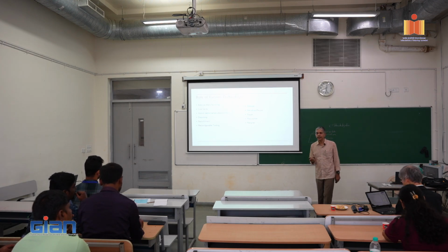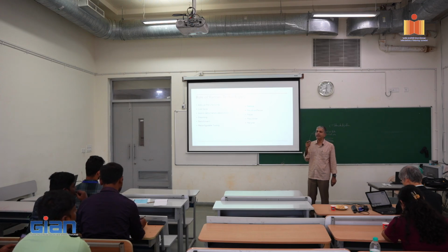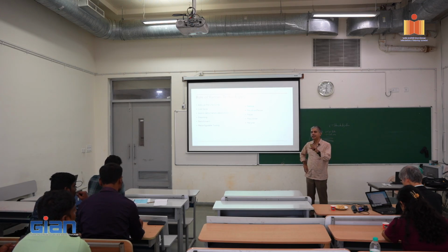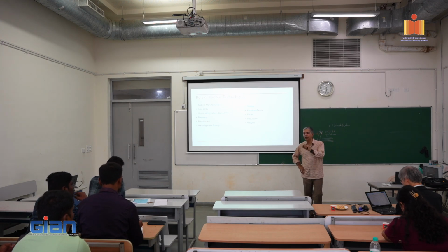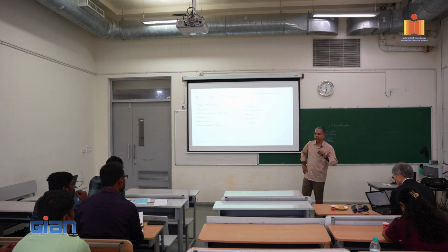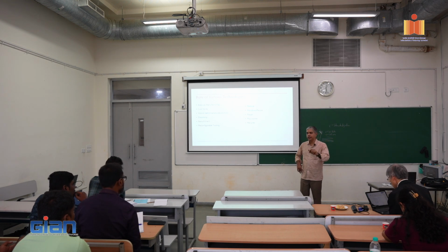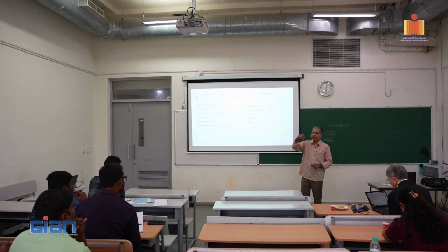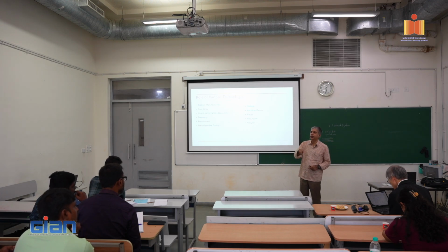What we do here is, as I was saying, the challenge in repair applications is the metallurgical condition. Is the material homogeneous? So typically what we do is deposit the material, capture the deposited weld pool using an IR camera and pyrometer, and link it with closed loop control of the laser power.